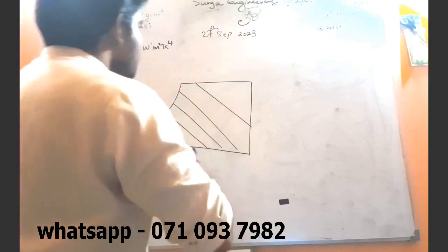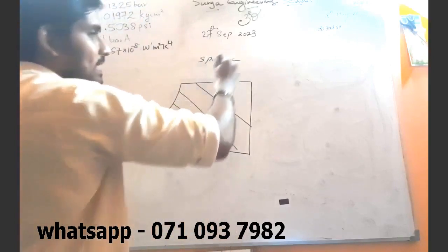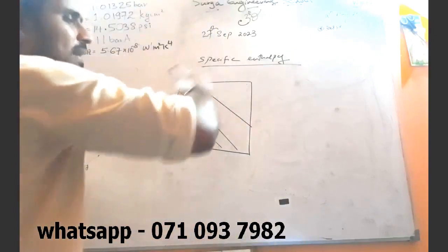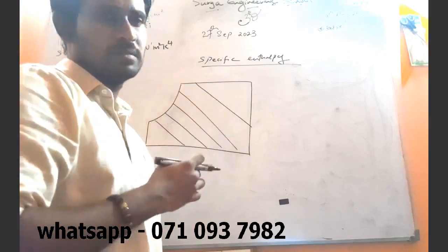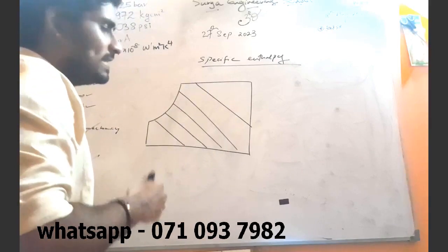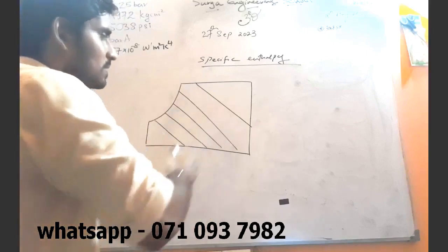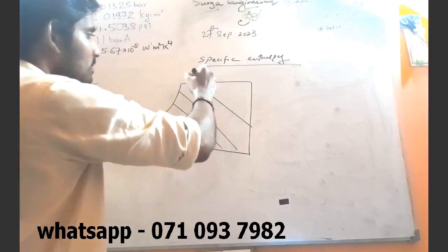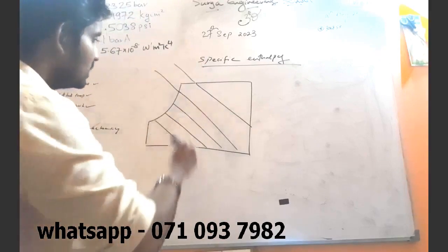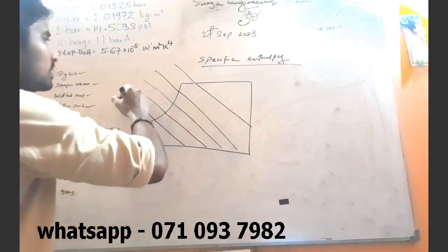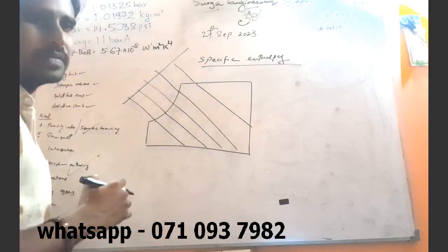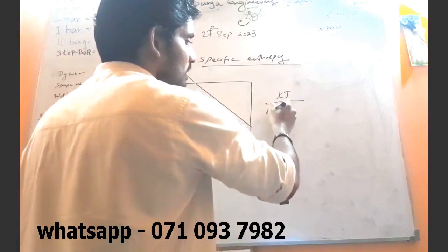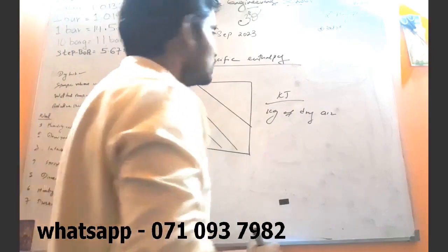Now if I consider the specific enthalpy lines, these lie very nearly parallel to the wet bulb temperature lines. The technique here is that the same lines you have sketched to denote the wet bulb temperature are extended to another scale. It is the same line, not a different line. That scale we refer to as the scale for the specific enthalpy. The units will be kilojoules per kilogram of dry air. So that's about the specific enthalpy.